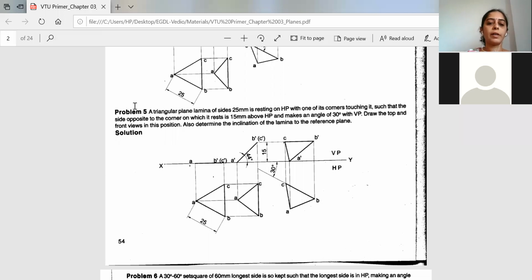Okay, so now after this, the first stage I've explained already. Then you leave some space. The 15 mm locus you have taken already. This point you fix as A dash. After this you measure this distance. Then, keeping the compass at this point, cut an arc for the distance you have measured. That will cut on the locus of 15 mm.